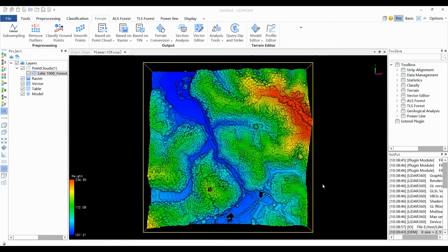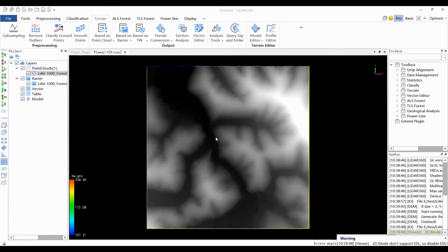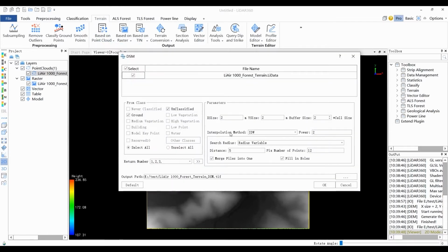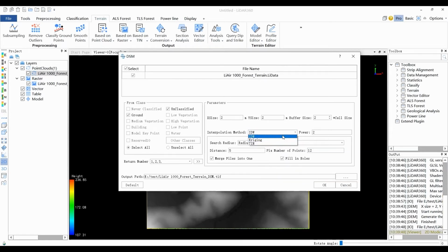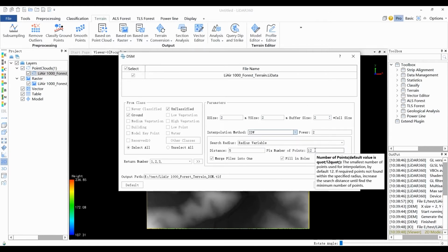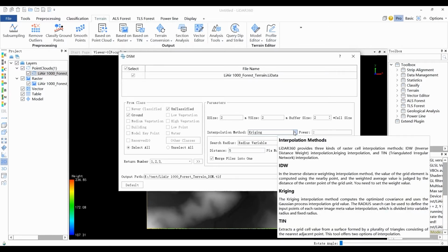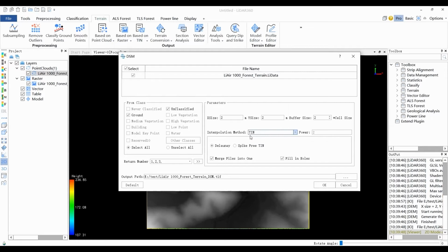A digital surface model refers to the digital representation of the height of the surface, including the buildings, bridges, trees, etc. Compared to a DEM, a DSM contains more elevation information for buildings, bridges, forests, and other surface objects that don't exist in the DEM. DSM is based on the DEM and further covers the elevation of surface information, other than the ground, same as the DEM. Please refer to the grid parameters section in the user manual for interpolation settings instructions.